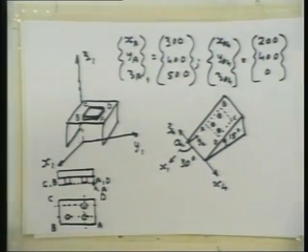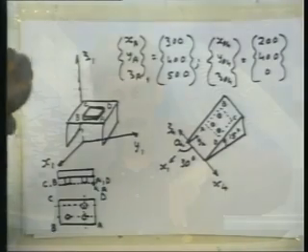What needs to be done is a gripper has to come, pick up the part, right, and take it to this position and to a position where you can now push into assemble. And what you need to do, if you remember the joint interpolation discussion in this class, in this course, the input for that to determine how the joints should move are certain locations of the end effector, right? From that we use the inverse kinematics problem to work out the corresponding joint angles or the joint variables, and those form the inputs for calculating this interpolation.